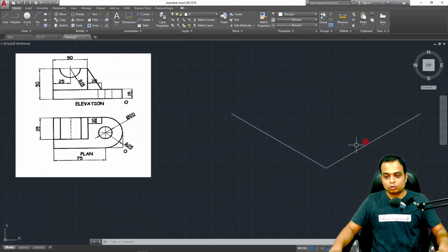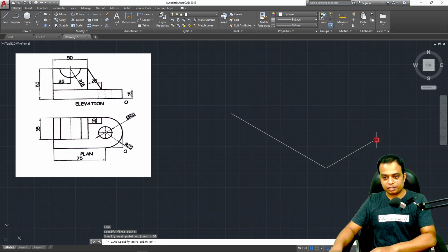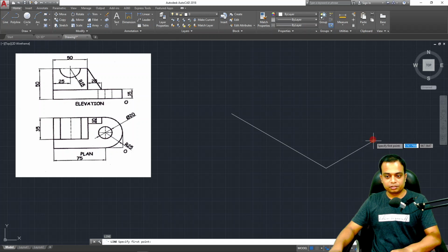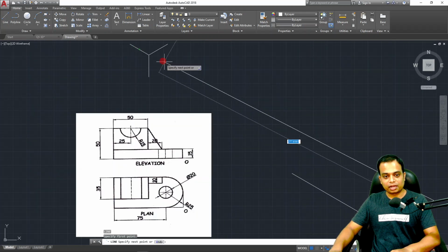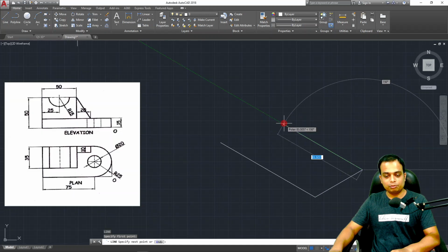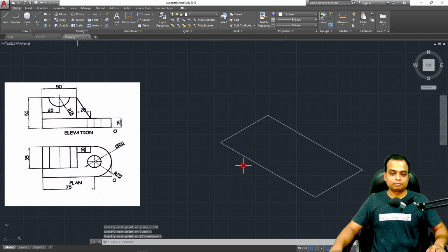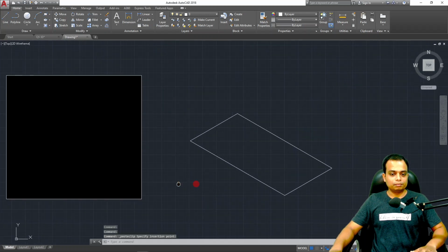Okay, so this is going to be for the width, which happens to be 50. Let me erase this. Let me use the line command again and let me go for width. Here it is 50. Done. Okay, now you just need to finish this again, move in this manner. Right now we are moving along this isometric axis. Okay, this is how you need to continuously monitor your mini drafter. This is 100 and back to where we start. Done. Okay, let me Control X, Control V.